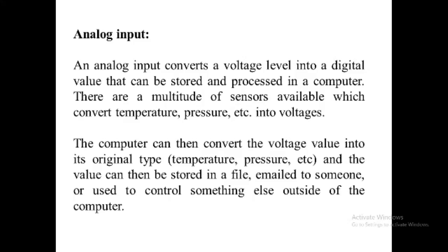The operation of analog input modules. The analog sensor produces a difference in resistance, current or voltage which is received in analog input modules and converted into a digital value that is stored in a memory word.